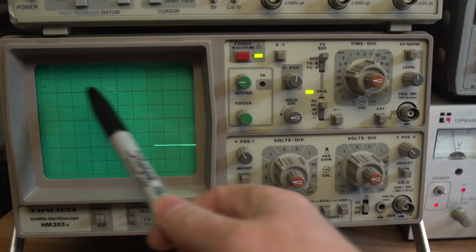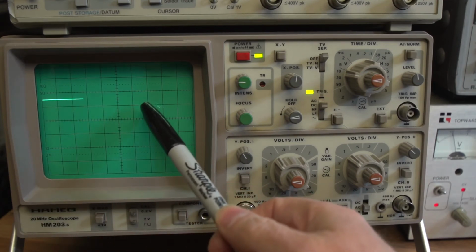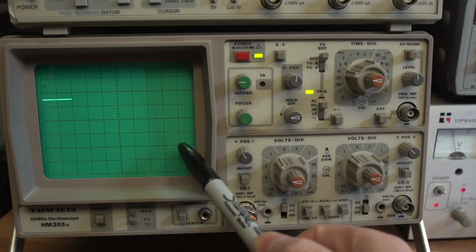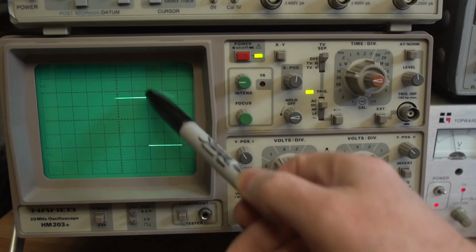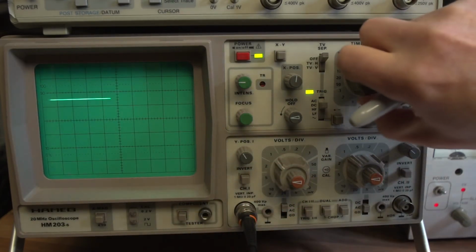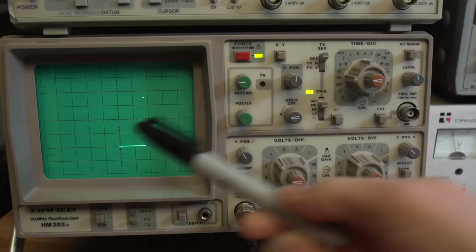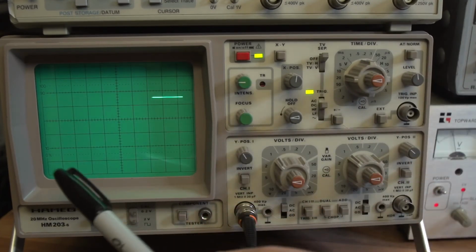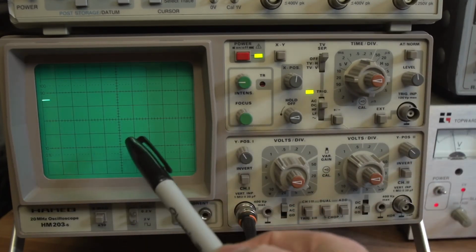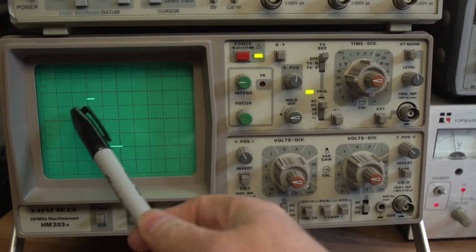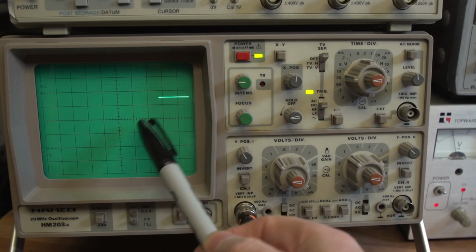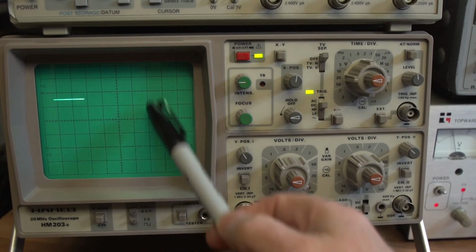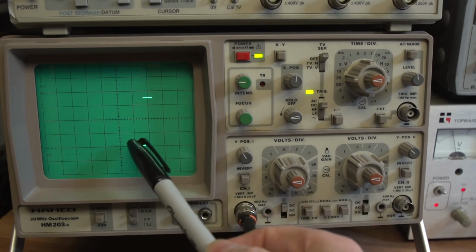We'll have a high voltage here, a positive voltage, then a very quick drop, and then a low voltage at the bottom. It's actually 0. So because we've got this very steep, sharp angle going on, I'll just reduce the time base so you can see more of the cycle, more of the waveform. You can see it's a square wave, basically. You've got a high, and you've got a low, and it goes high again, with very sharp fall and rise edges. Okay, so that's a square wave.